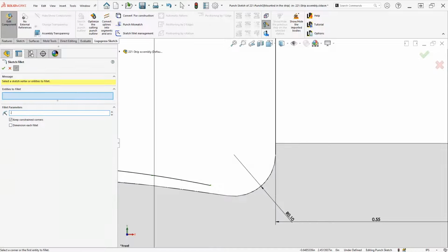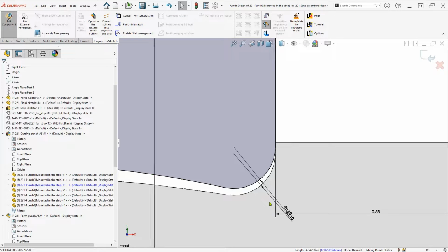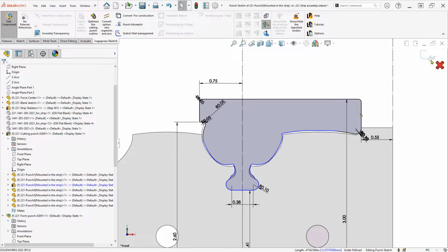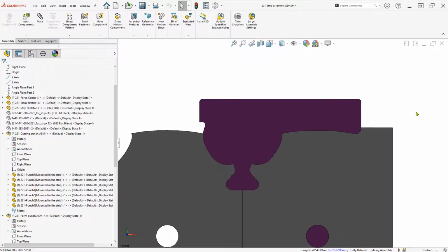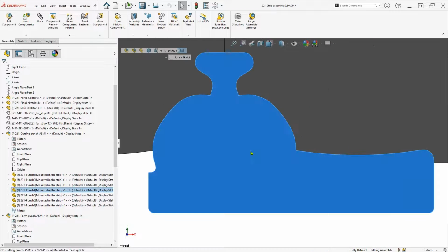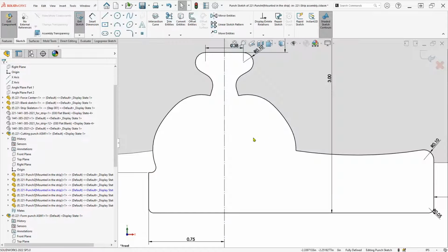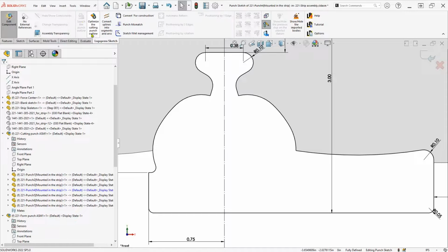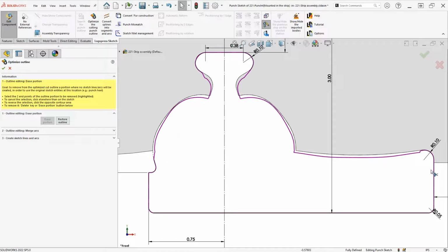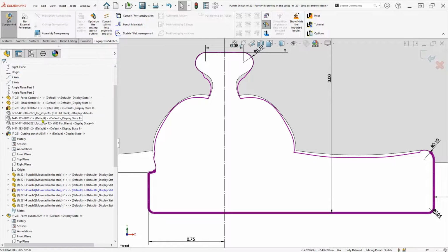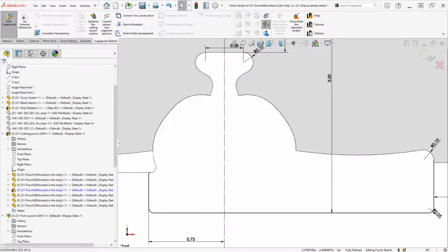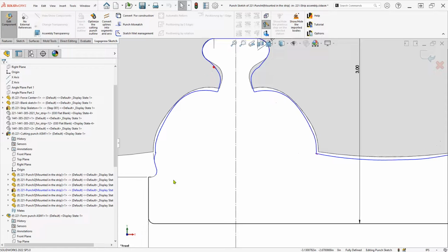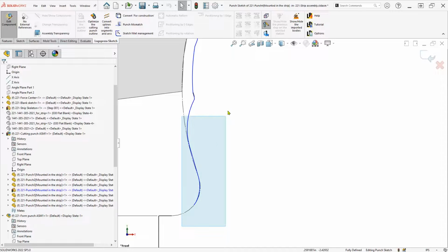There was a little overlap where the two cutting punches overlap, so it wasn't necessarily an optimized shape right there on the edge, but you can clean it up with the fillets. And then the LogoPress strip layout adjusts all the cutting in the stations here, just as you would if you were editing the punch for another shape that you put in there, regardless of the optimizer. Do the same thing on the backside punch here. I'm going to remove this back part again, stick with the initial input geometry, and then connect the new optimized geometry to it.